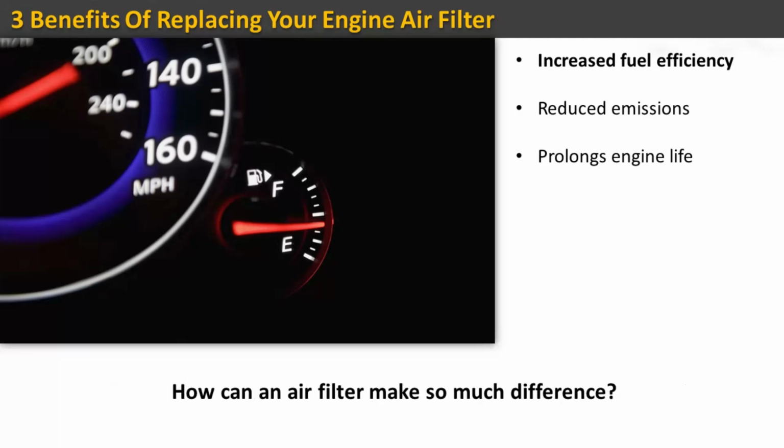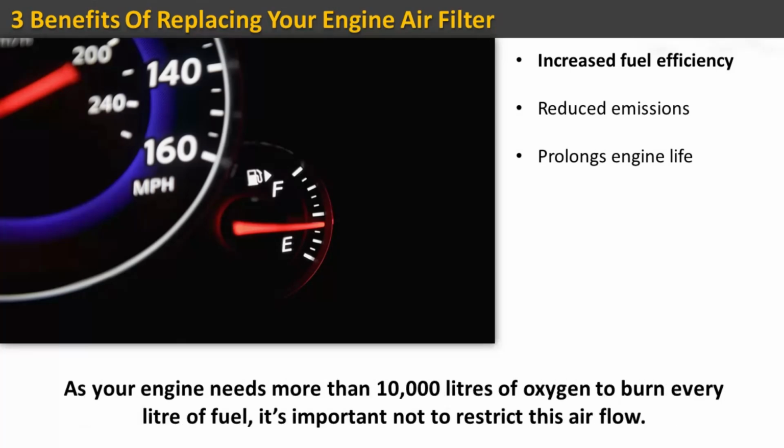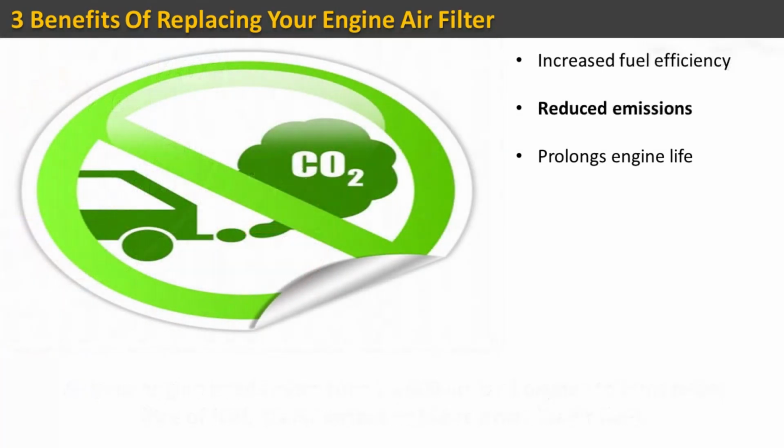How can an air filter make so much difference? A dirty or damaged air filter limits the amount of air flowing into your car's engine, making it work harder and, therefore, using more fuel. As your engine needs more than 10,000 liters of oxygen to burn every liter of fuel, it's important not to restrict this airflow. Reduces emissions.